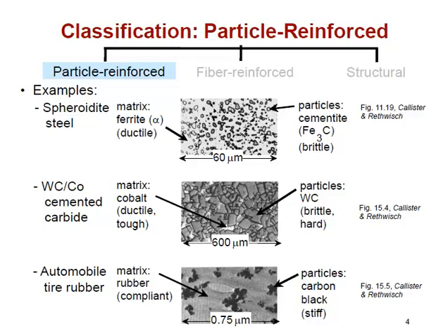So if you remember spheroidite, the long duration heat treatment product that comes from tempered martensite held at temperature below austenite temperature for long durations, that is actually an example of a spontaneously formed particle reinforced composite, where those cementite round particles strengthen the ferrite matrix. They're very fine dispersion, and so they can stop dislocations and also add a little bit of fracture toughness.